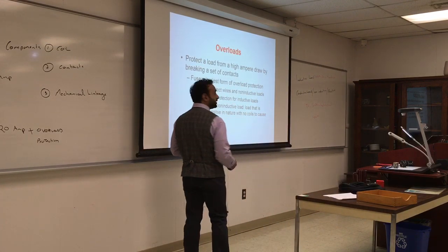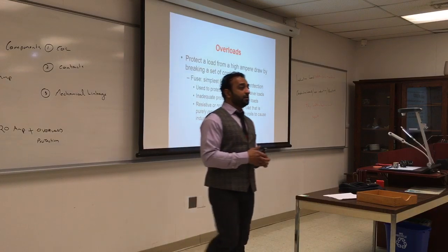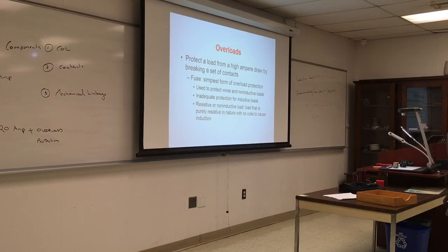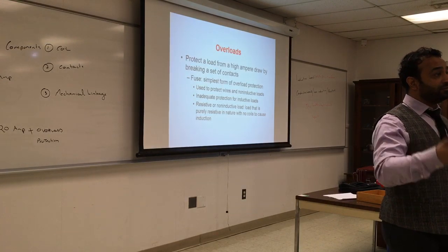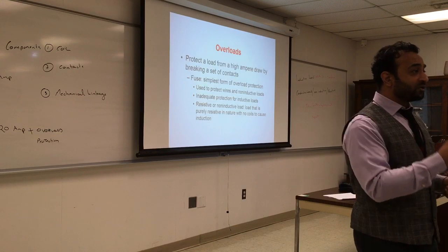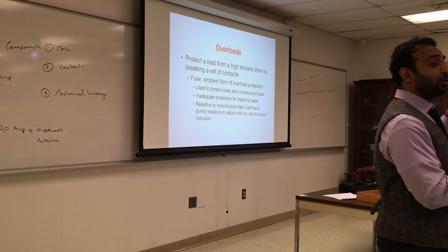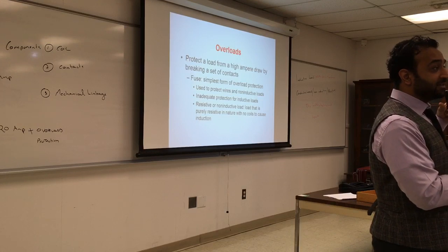It's not adequate. We can still have a fuse, but it should account for the spike. So we have a locked amperage and we account for that. It's going to be the last measure. We're going to have an inductive load and we also can have a fuse. If you look at some circuit breakers, they have a circuit breaker and also have a fuse. The fuse is going to be oversized. It's for extreme cases.